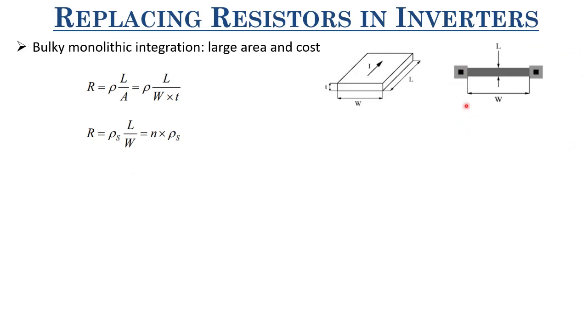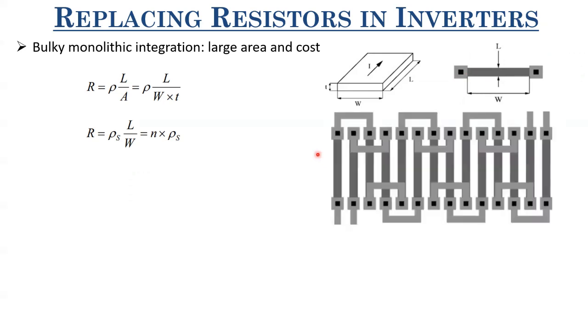The ability of the tool to reproduce the same resistance will not be efficient. If they are separated by a large distance, because of process variation, they won't be matched. So in order to match these, people use interdigitated types of resistors. Here they combine the resistors. Let's say the first resistor is going like this, right? So it's going like this.